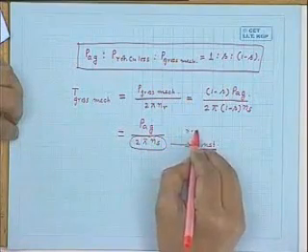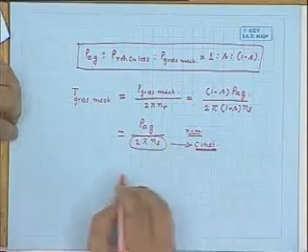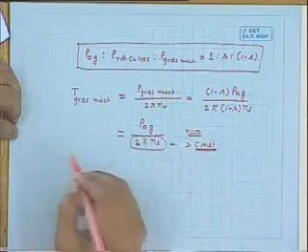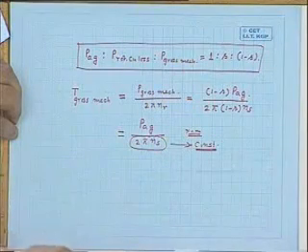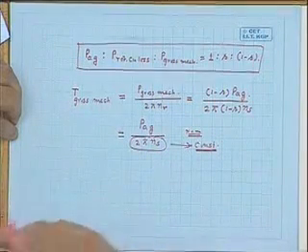The unit of this one will be what? Torque unit will be Newton meter. But sometimes torque is also expressed in synchronous watt. That means if air gap power in a particular machine is, say, 1000 watt, you tell also torque developed is 1000 watt.